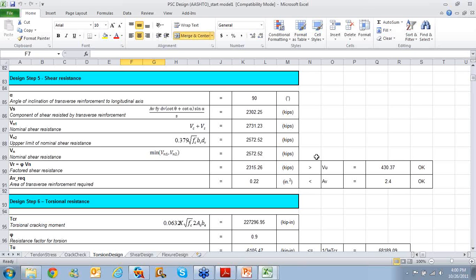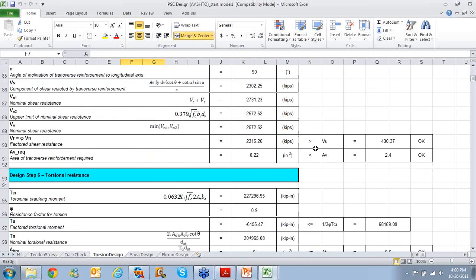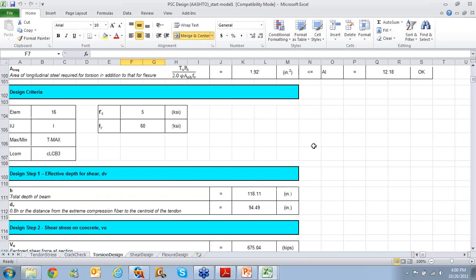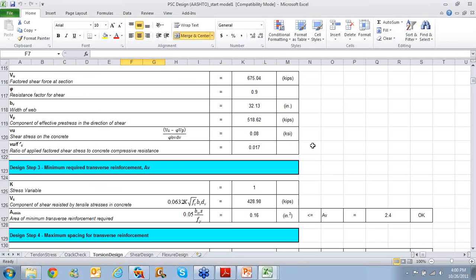You can even check whether the sections are oversafe and reach an optimal design through a little bit of iteration process for concrete sections, because this will tell you whether your section is good or not, and once it says not good, then you can investigate what can be the causes, and then based on that you can either modify the geometry or change the section dimensions, or reduce the prestressing or increase the prestressing, or add or take out the rebars from those particular sections. And this PSC design tool is very helpful for reaching these kinds of iterations and converging the design in no time.